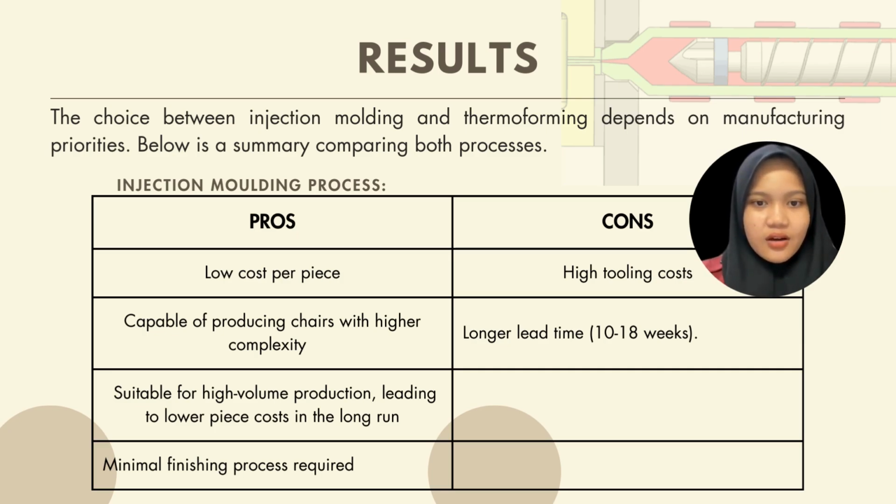For the cons, it has a higher initial tooling cost. The cost of creating the mold is substantial, making this process less suitable for low production runs. It also has a longer lead time, within 10 to 18 weeks.